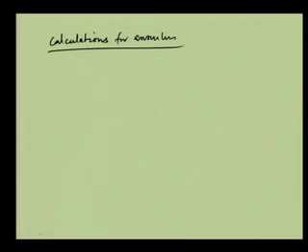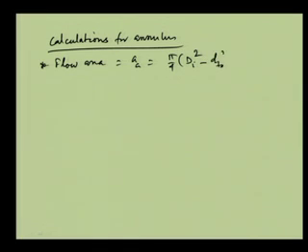Then we have calculations for the annulus. Okay. In the annulus, what about the flow area? That is to be calculated. This is pi by 4 into, say, DI square, that means inner diameter of the bigger pipe, minus the tube outer diameter, whole square.